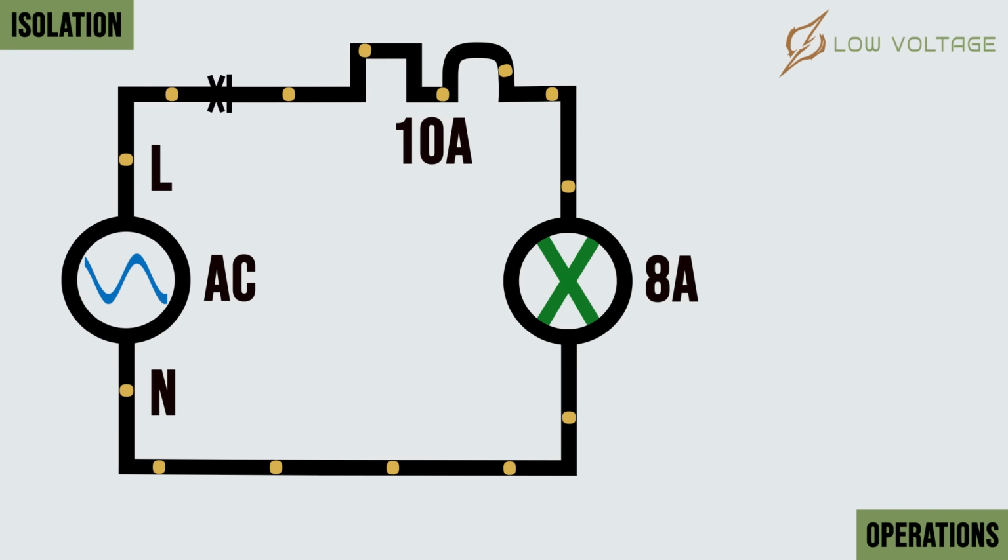Another MCB operation is called isolation. Isolation is simply switching the handle or knob to off position, thus cutting the power between the supply and the load. When the MCB is switched off, the flow of current stops, but in fault-free conditions. This operation allows maintenance for the load, conducting lines, and terminal connections.